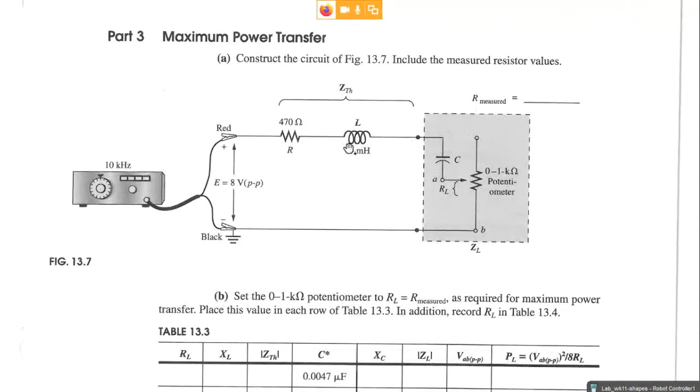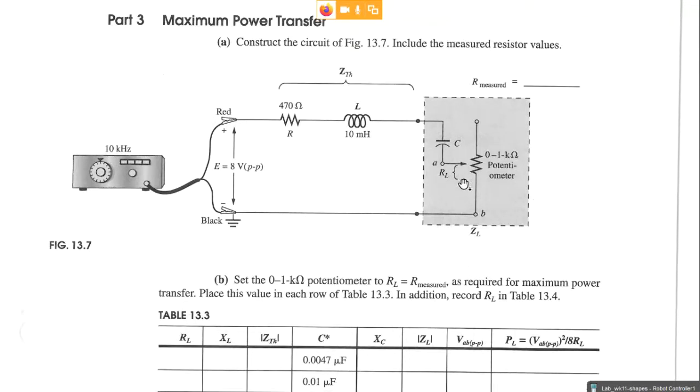But all right, so here maximum power occurs when, if you have an inductor and a resistance, which of course we do have here, so you have an inductance and resistance for Z Thevenin, then what you need to do is find the capacitance that gives the exact same reactance and put that in there. So we use what they call the complex conjugate of that. Okay. And so we're going to put in a capacitor in series with RL.